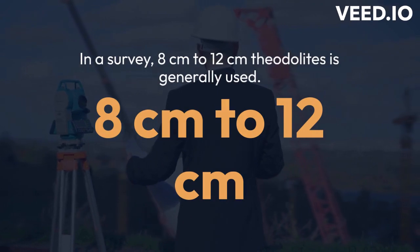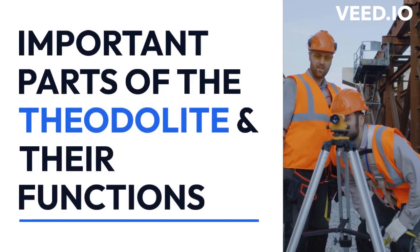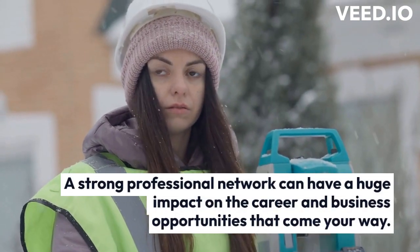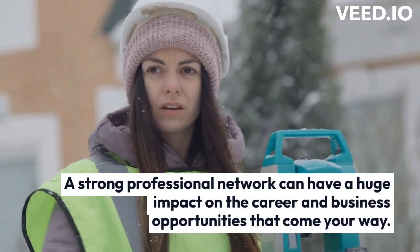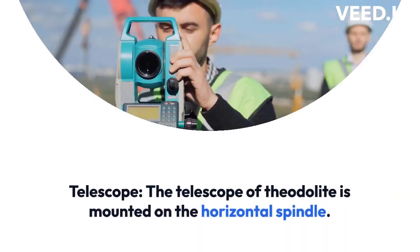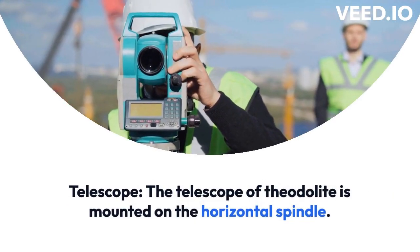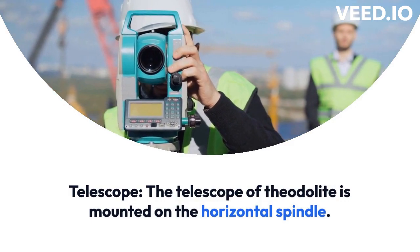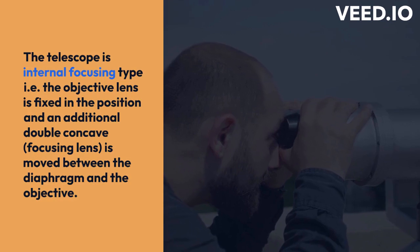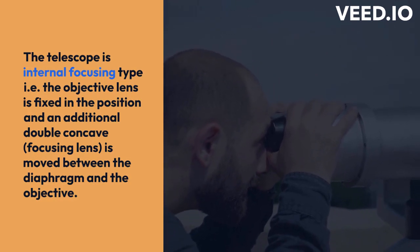Important parts of the theodolite and their function. Telescope. The telescope of the theodolite is mounted on the horizontal spindle. It can be rotated about the horizontal axis to sight the objects. The telescope is internal focusing type, i.e., the objective lens is fixed in position and an additional double concave focusing lens is moved between the diaphragm and the objective.